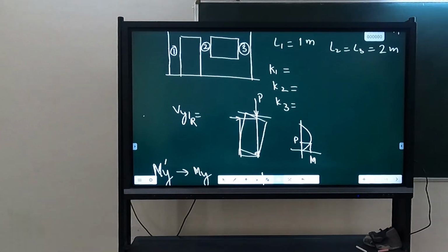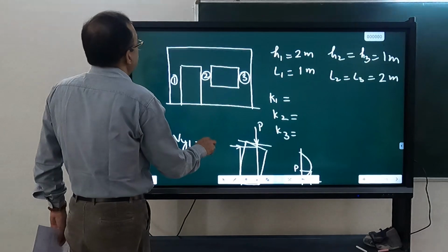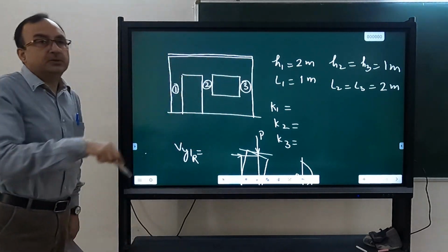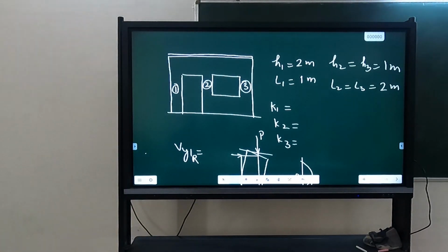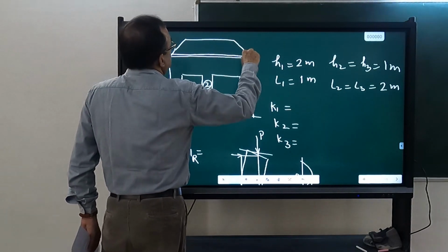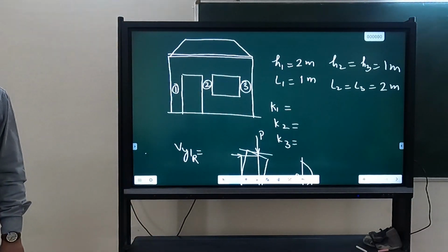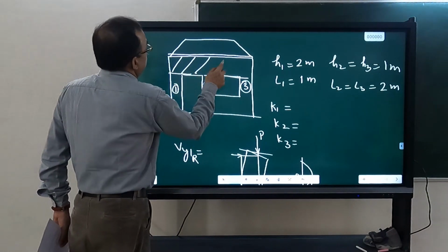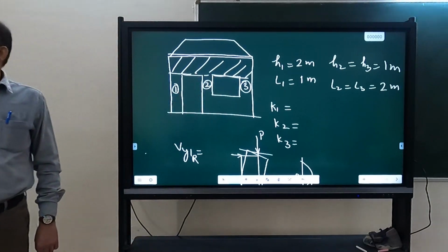So what you need to know is the axial load. How are you going to get the axial load? Weight from the top. Weight coming from the top, you have to perform analysis for vertical load. So there is a slab at the top. That slab load you will distribute in an inline pattern. That will give you the load coming from the slab at the top. Then on this pier, you will see that this pier load will also come.